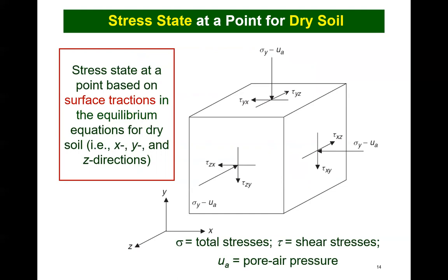The above series of slides shows us that there is a smooth transition between saturated and completely dry soil states. The transition points are defined in terms of degree of saturation of the soil and the continuity of the fluid phases. The two most important points are the air entry value of the soil and the residual stress state.